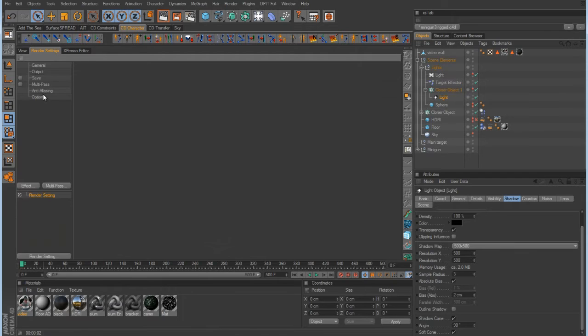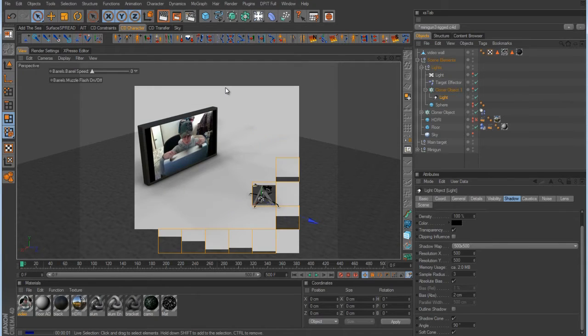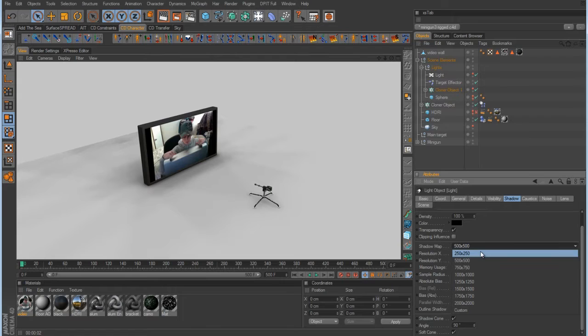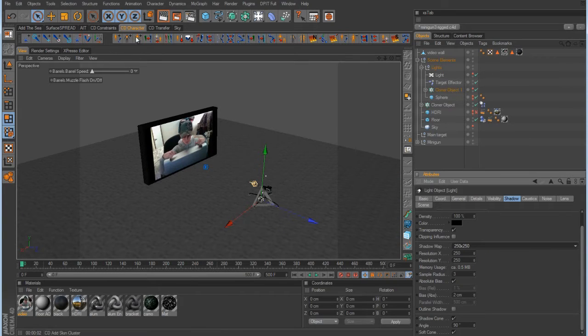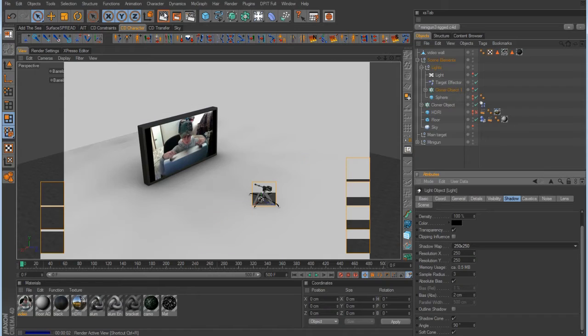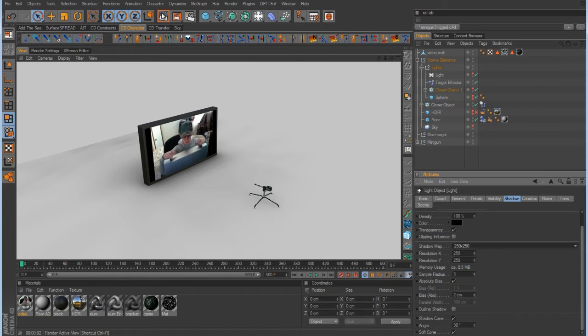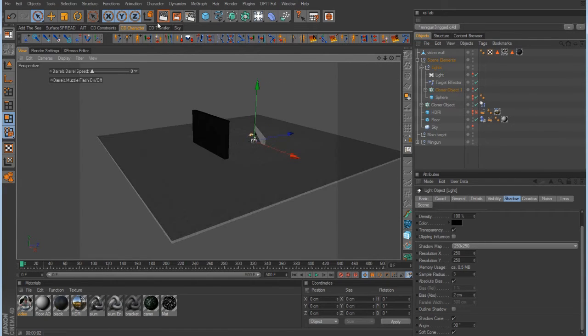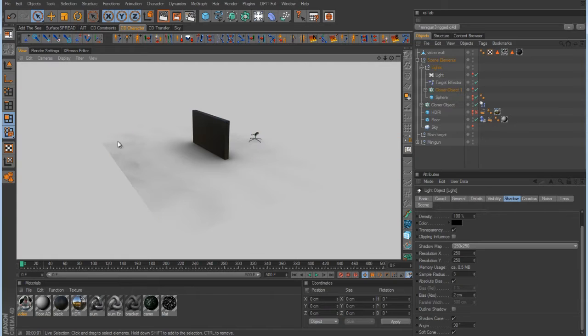So what I'm going to do real quick is just change my anti-alias settings to best. I want to be able to view the shadowing without any jagged lines in it. Okay, so we want to be able to fix this so we get nice soft shading versus all of these lines. So let's just try something like a value of 250 by 250 for the shadow map. Okay, now that eliminated quite a bit of it, but we're still getting some unwanted stuff back here on the back side. You can see we've got some really nasty looking stuff going on right there.